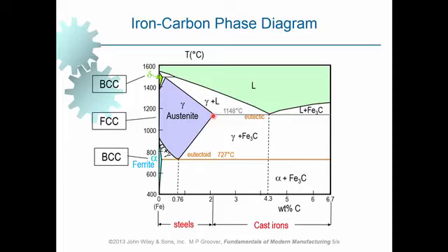And what is meant by this? It means that for this given type of material, at this temperature, we can accommodate a significantly larger number of atoms of carbon in the crystalline structure of the base metal. A larger number of atoms of carbon can be accommodated in void spaces of the atoms of iron. And this is used in heat treatment processes of steels.